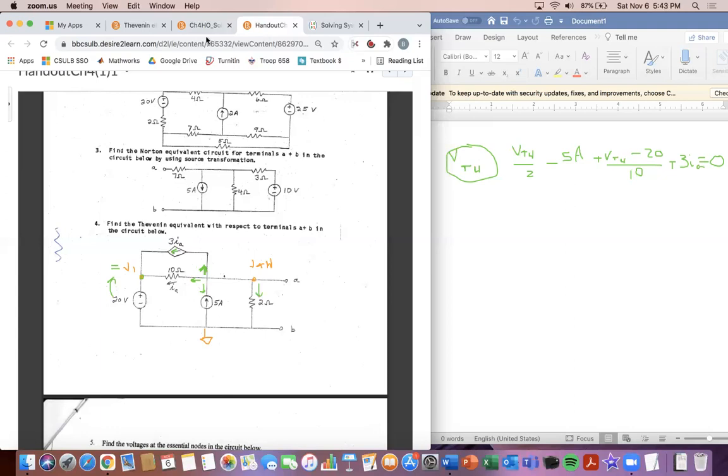I made that same error, Fady, and I was noticing in the textbook they made it simpler because look here, these are connected, right? This 2 ohm resistor is right here. If you pretend it's not here, you can see how it's connected to A here. They're all connected right there. So technically, this node for V Thevenin, you can draw it anywhere along that line because they're all connected. I could draw it here, I could draw it here. It's the same exact point because it's all connected along this one branch. So you can draw that V Thevenin where you want to.